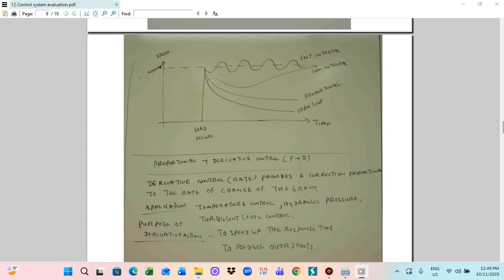Open loop control means that without providing any control machine, when you put more load, the motor speed goes down and nothing moves the speed up. So this is the comparison between integral control, open loop control, and proportional control. Those kinds of control systems are utilized in industry, especially to control motors.